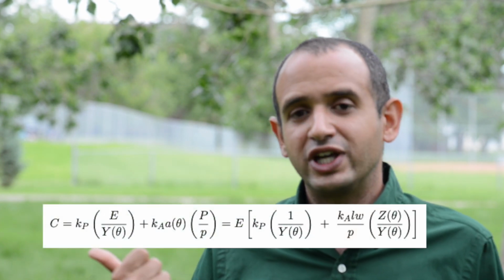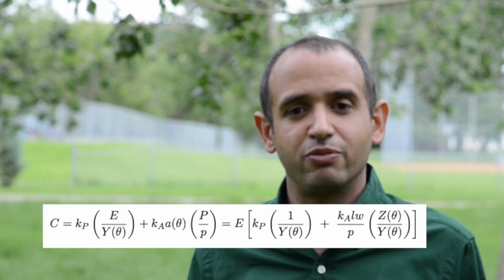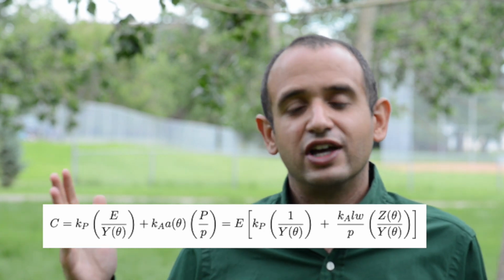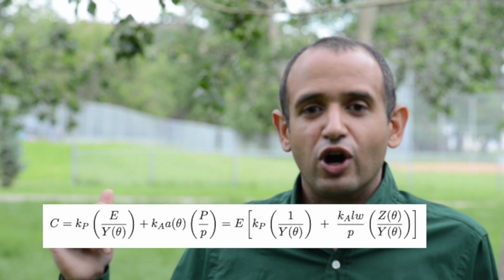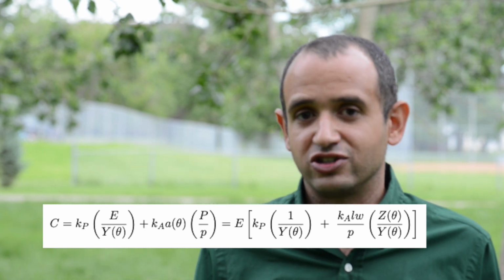Up to this point, I've been talking about minimizing the total cost, but typically solar designers use levelized cost as their caliber when designing solar PV systems. So let's look at minimizing levelized cost instead of just minimizing cost. Again, if we go back to our expression for total cost, we can see that the total cost is directly proportional to the total energy requirement. And because levelized cost is total cost over total energy, dividing the right-hand side by E will yield the same result because, again, it's a constant.